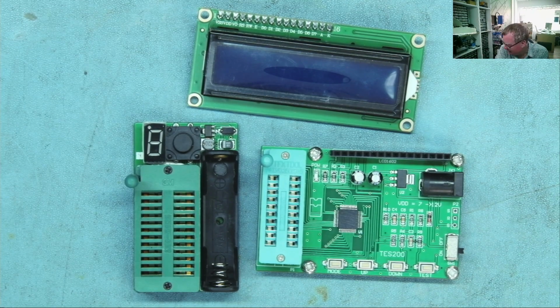So where does that leave us? Well, I've tried all the things that you guys suggested, and didn't really get anywhere with that. I've tried what I thought as well and didn't get anywhere with that. I think there's something very strange about those chips. The fact that the Q and not Q outputs, when it goes high, go to a strange voltage of 2/3 supply voltage. My thought is a defective batch of chips. And the only way to prove that now, because we don't have a tester, and let's face it, we did build a breadboard tester and it failed, is to order some more chips. So I'll get on and do that.